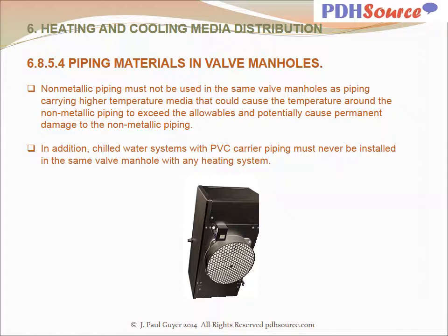Non-metallic piping must not be used in the same valve manholes as piping carrying higher temperature media that could cause the temperature around the non-metallic piping to exceed the allowables and potentially cause permanent damage to the non-metallic piping. In addition, chilled water systems with PVC carrier piping must never be installed in the same valve manhole with any heating system.